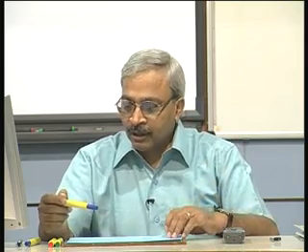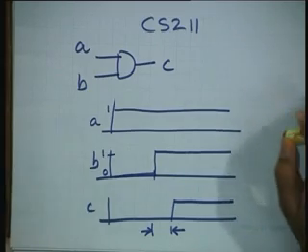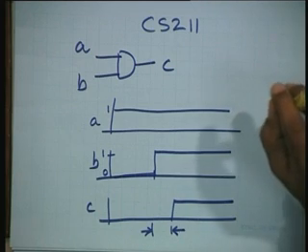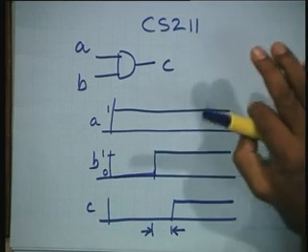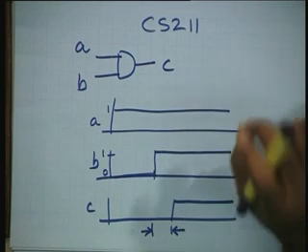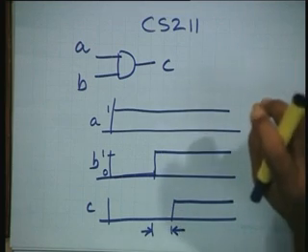On the other hand, if the gates were working in nanoseconds or larger, then the wire delays may be negligible. For the present discussion, we will assume that wire delays are not significant, because our focus is on the logic part of the design, and we will take into account the delays which are caused because of the gates.